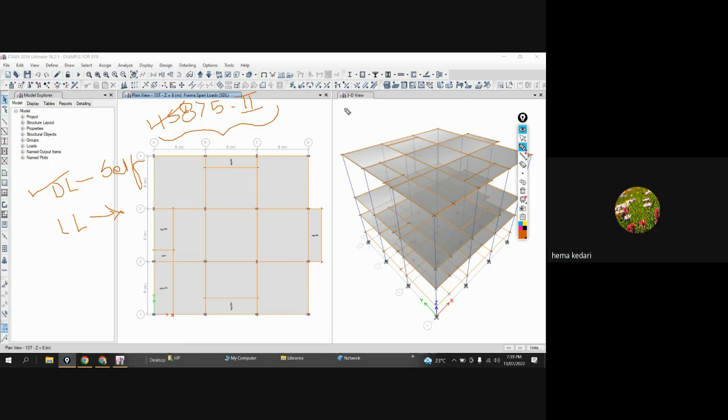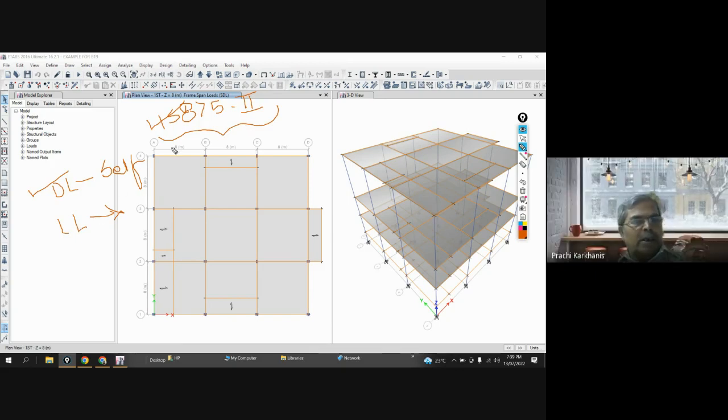Yes, sir. Okay. Now, this live load category under residential, we are following 2 kilonewton per square meter for rooms in a residential building, maybe bedroom, living room, kitchen, etc. Then for balconies and passages, they say that, subjected to overcrowding, the loading intensity that you have to provide is 3 kilonewton per square meter.